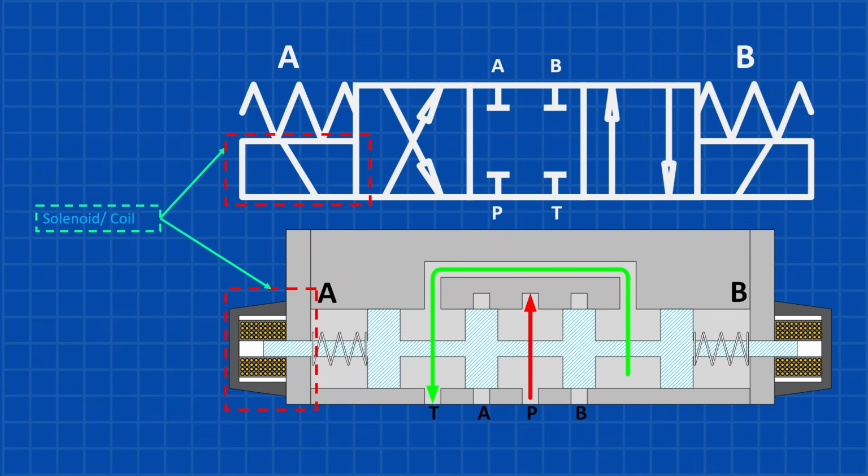In applications using a single solenoid spring return valve, the coil must remain energized to keep the valve shifted. Excessive heat from overvoltage, high ambient temperatures, or an incorrect coil can eventually damage the insulation and cause the coil to fail.